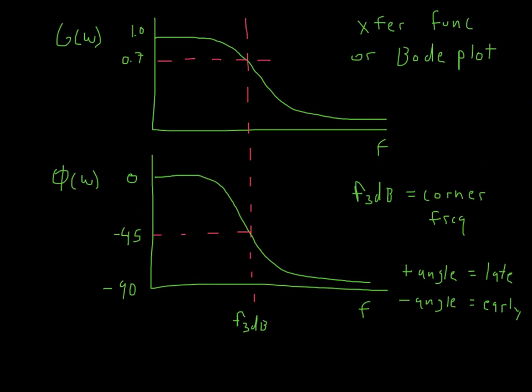Okay, and now I promise this is the last slide. These are the plots of the magnitude. This is the magnitude of the gain as a function of frequency, f. So again, omega is 2 pi times f, and typically in lab we measure f, we don't measure omega. But we could change it into omega if we wanted to. And here's the phase as a function of frequency. So this is for our low-pass filter. What this means is for low frequencies, there's a gain of 1, and those frequencies get through. But as we turn up the frequency, it starts to attenuate, and it goes to 0.